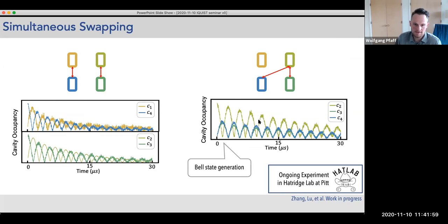So in this case, it's a three-wave mixer. It turns out that the different cavities are all in the order of 6 to 7 gigahertz. No, actually, in this experiment it's a bit wider, say anywhere between 5 and 8, for example. That means the pump frequencies themselves are any difference between those, so it's a relatively low frequency. In the order of 1 to 2 or 3 gigahertz is the pump frequency. So any of the differences, basically.